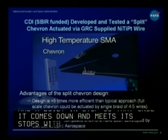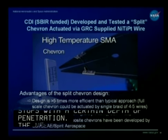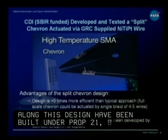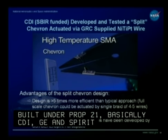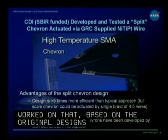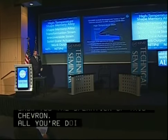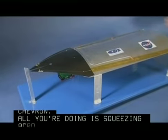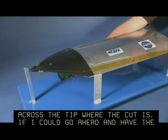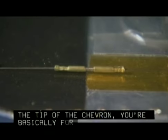Now, next generation chevrons along this design have already been built under Prop 21. Basically, CDI, GE, and Spirit Aerospace worked on that based on the original designs we have. But if we could have the movie, I'll show you the operation of this chevron. Basically, all you're doing is squeezing across the tip where the cut is. So as you squeeze across the tip of the chevron, you're basically forcing it down and causing it to deflect. So it's, again, a very simple design.